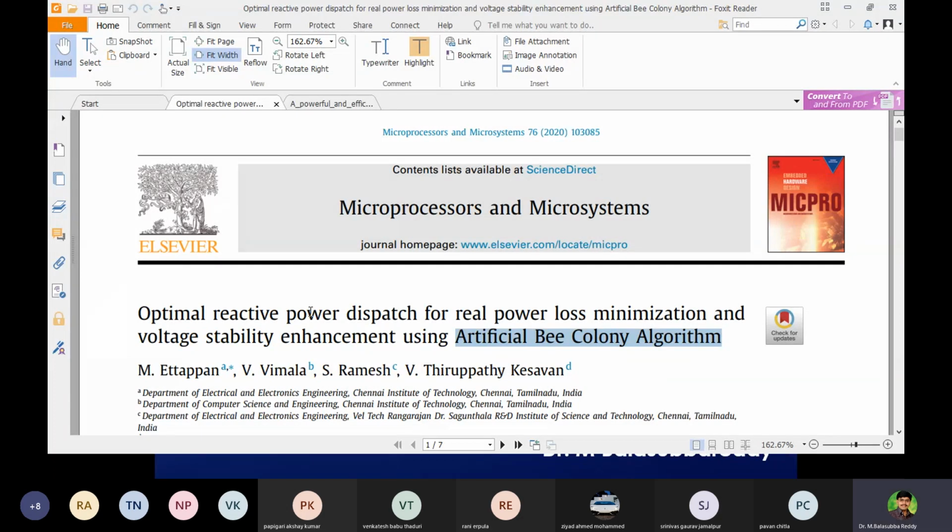Now if you generate 10 megawatt of power through generator 1, 20 megawatt through another generator, and the third generator may be 50 megawatt, and so on, what is the cost of generation? In the general expression, we simply substitute it as f of PG1 equals A1 plus B1 PG1 plus C1 PG1 square and so on. You substitute the PG1 value, and with the A1, B1, C1 values you get the cost for the first generator.